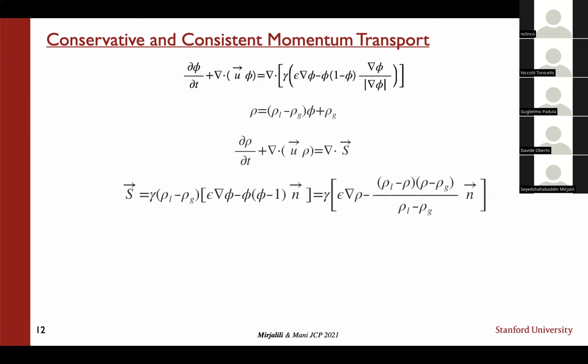The idea is beyond that: even on the PDE level, you are not conserving kinetic energy when you don't account for this term. You do gain by using a skew-symmetric formulation of the advective term, but you don't really need it for the staggered configuration we're dealing with here and incompressible flows.